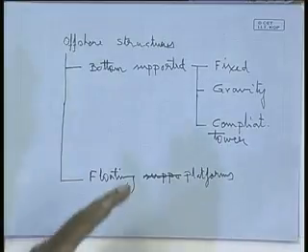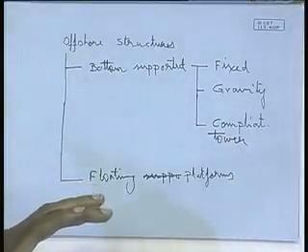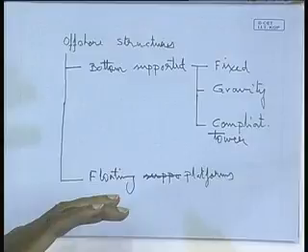That is how the fixed towers are, fixed in the seabed. That means the legs are grouted in the seabed. Once the tower is taken to the site, it is literally fixed, cemented to the seabed. Obviously, they are generally used at very shallow depths, of the order of 15 meters, 20 meters, like that.